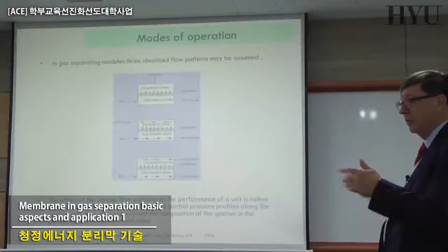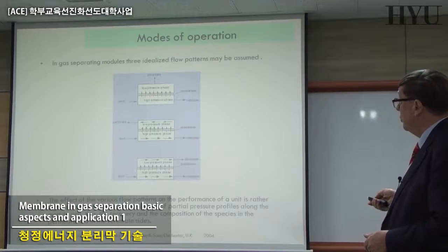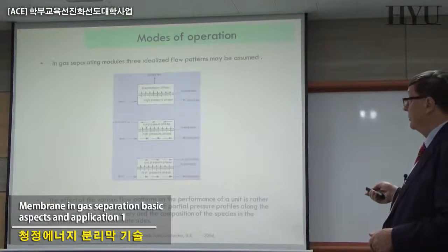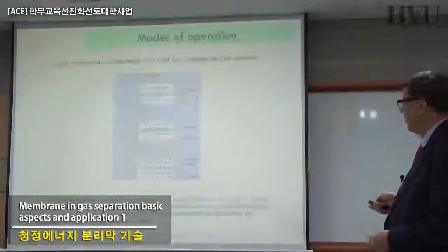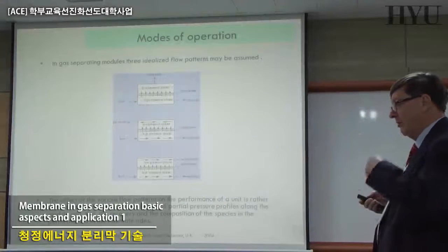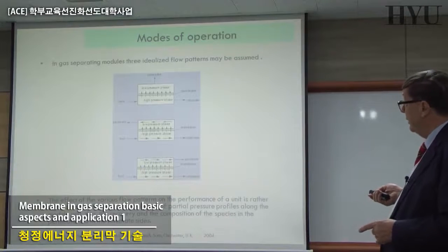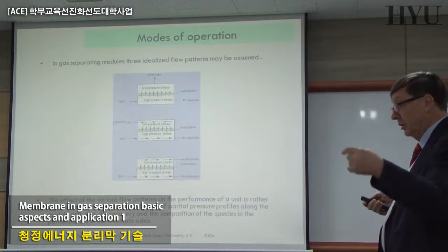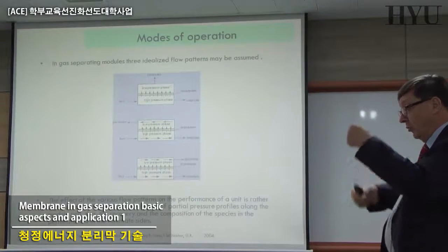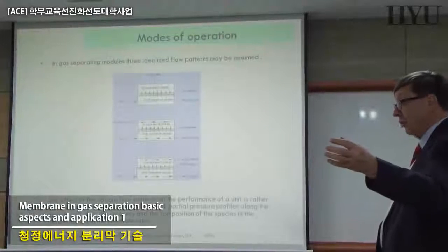That's exactly what we had in ultrafiltration, microfiltration. You can have the same system in which, on the permeate side, you can also have your fluid, your permeate, moving cross flow on the membrane surface. And you can go in co-current and counter-current if you want to keep control of the driving force along the length of your module.